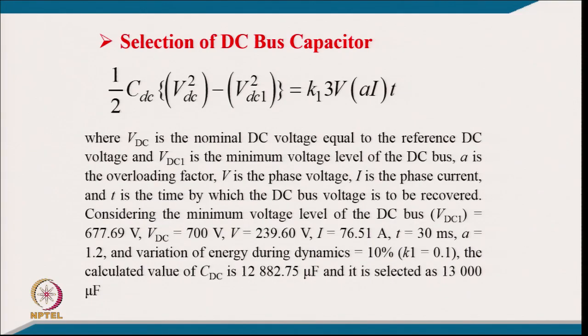Well, as far as selection of the capacitor is concerned, there are many criteria. These are virtually the design guidelines we consider. One of the criteria is the ripple voltage corresponding to the harmonics, where you might have the lowest, second harmonic. Corresponding to that there will be a ripple voltage, which we will discuss also, but the very important, stringent requirement is the dynamic variation of the voltage.